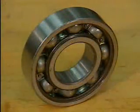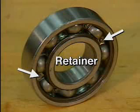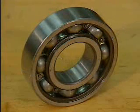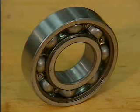The rolling elements are held in position by the retainer, which you may hear referred to as a separator or a cage. The retainer positions the rolling elements evenly around the rings and ensures that the load is distributed equally on each rolling element when the shaft is turning.